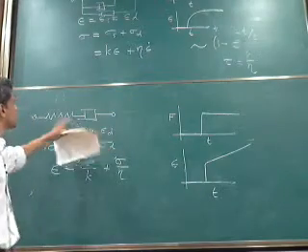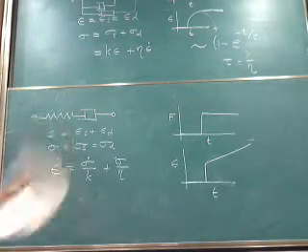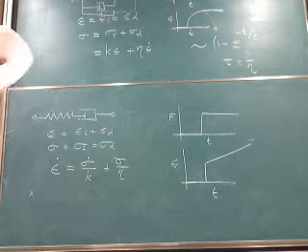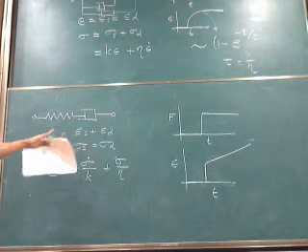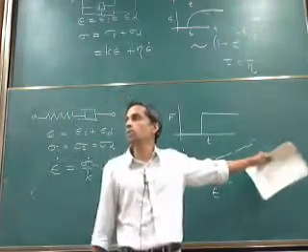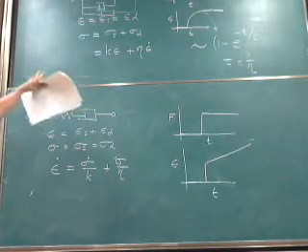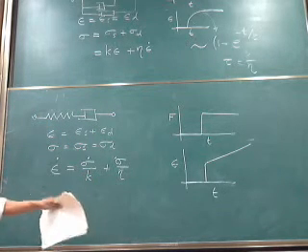The difference between that case and this case is that there, if I apply a constant force, irrespective of how small or big the force is, there is an equilibrium. There is an equilibrium strain or equilibrium length. The system does not keep extending forever. But in the second case, that is not what is happening. I apply a small force, it can be as small a force as I like, but the system will keep extending forever. The more I wait, the more the strain becomes. So that class of materials are called viscoelastic solids, and this type of materials are called viscoelastic liquids.